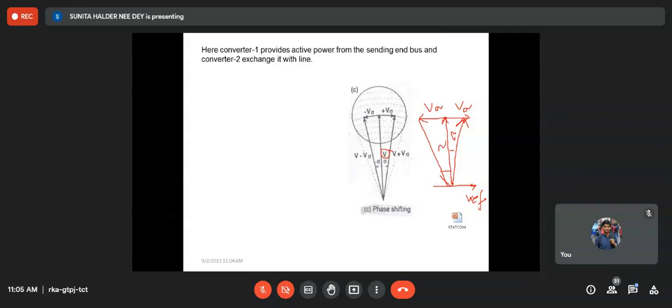In that way, using the series voltage injection, say you have learned the critical load angle, the maximum load angle we must provide for a Pmax. Then what will that be? That can be controlled using this series voltage injection. We can make the maximum power transfer before 90 degrees, even at more than 90 degrees, because artificially we are creating 90 degrees using this series voltage injection.